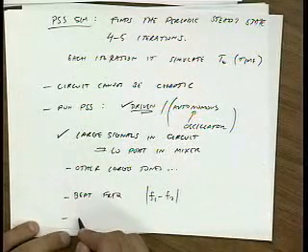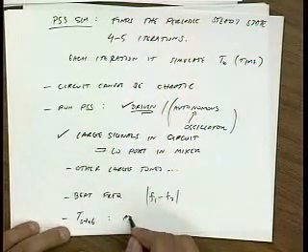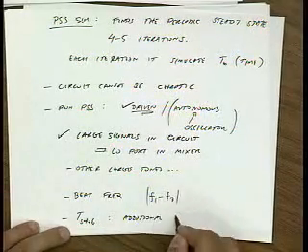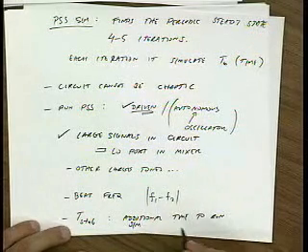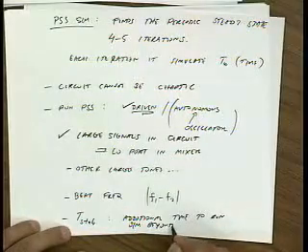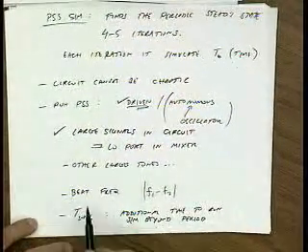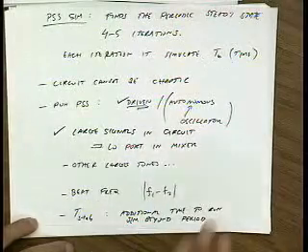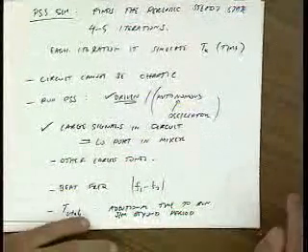Finally, you could give it a parameter called T-stab or T-stabilization. This is additional time to run simulation beyond the period. And this is useful for oscillators. It's not really that useful for mixers, so you can more or less ignore it. Okay. So any questions up to here on what periodic steady state analysis is?